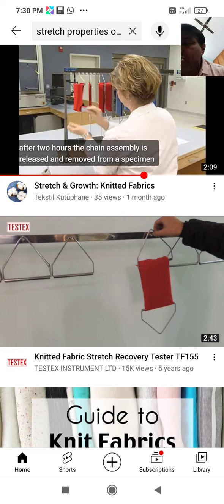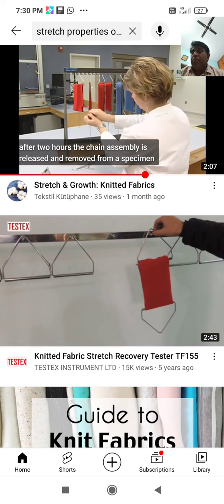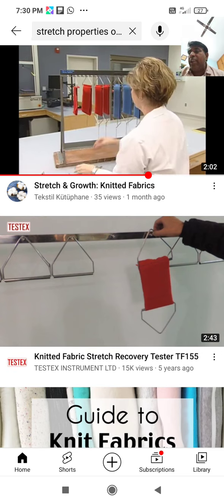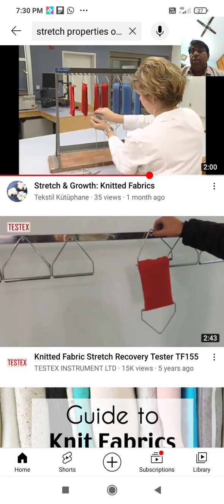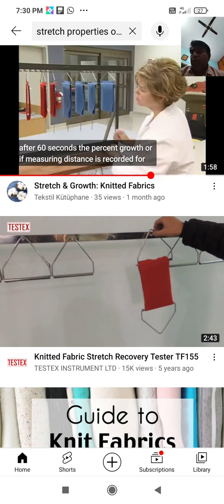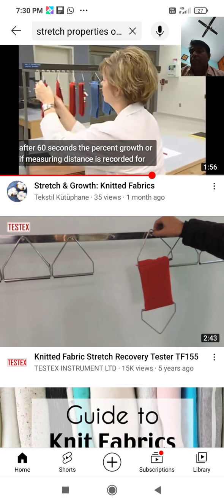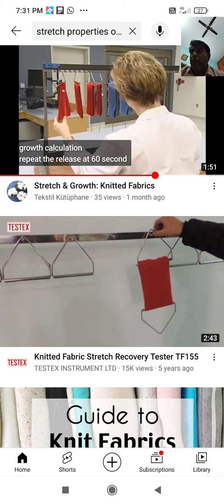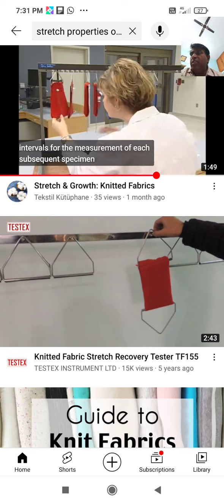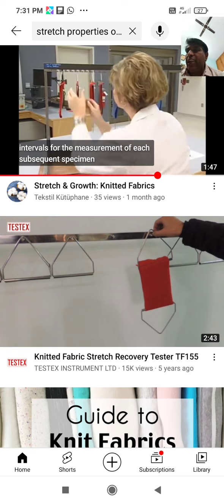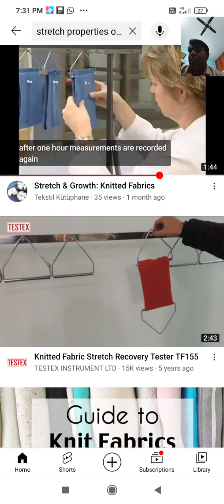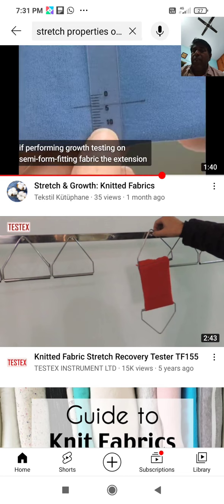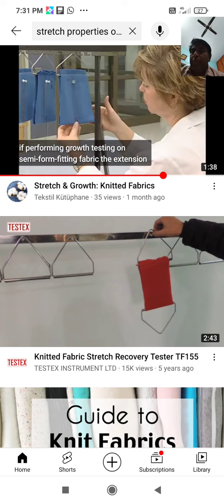To test the strength of a bond, specimens of size 15 by 7.5 cm in the length direction are taken. Then the 2 layers of the fabric along 7.5 cm are separated approximately 2.5 cm. The separated layers are subsequently held in the testing machine jaws and separated for 10 cm length at the rate of 30.5 plus or minus 1.2 cm per minute.